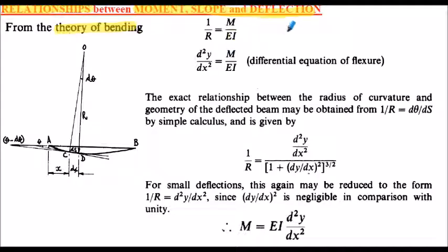We know from our previous simple bending equation we can have an expression of 1/R is equal to M/EI. By transposing the engineer's bending theory equation, it can be shown that 1/R could be written as a second order differential equation, so that d²y/dx² is equal to M divided by EI. This is known as the differential equation of flexure. And you'll see in the Macaulay's method approach, we will start each of our expressions from this second order differential equation. Just want to highlight this point to you.